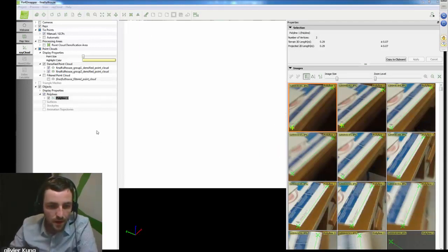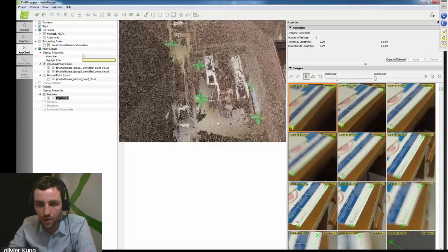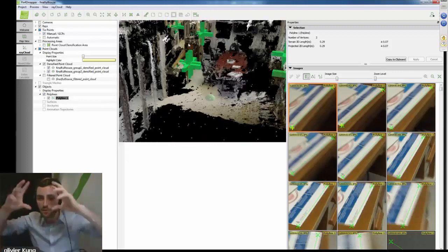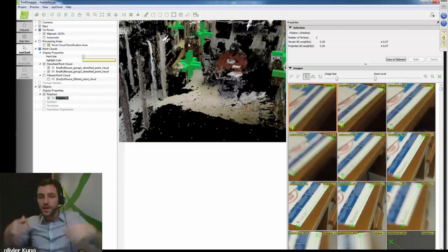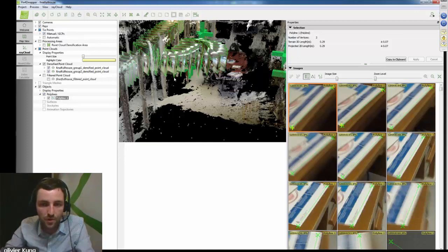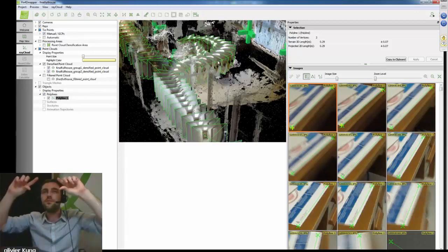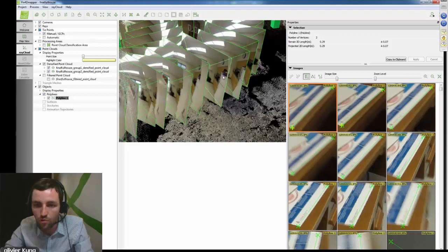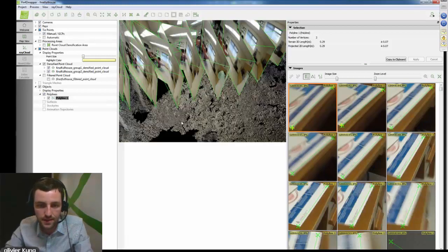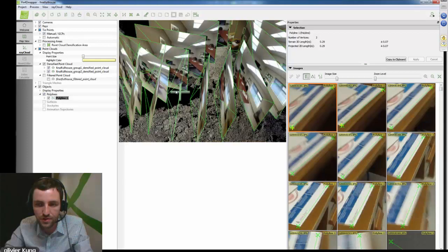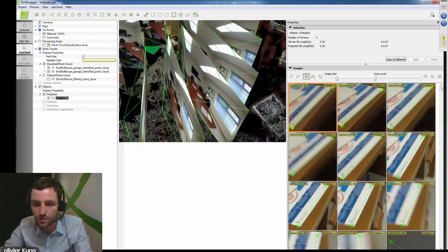All right. When shooting inside of a building, should we also move forward and not just pan the camera? That could be difficult to do inside of small rooms. Indeed, you should always move the camera when taking the pictures and not just rotate around. That's why we usually recommend a fisheye camera. With a fisheye camera, you don't need to take the pictures up and down. You basically cover the whole room in one single shot. And the distance that you move between each picture doesn't need to be very big. It can actually be just a few centimeters.